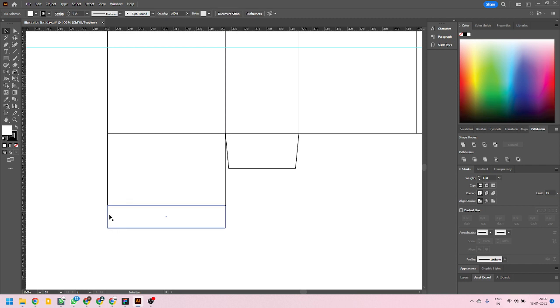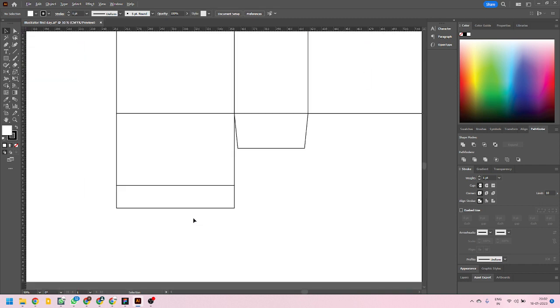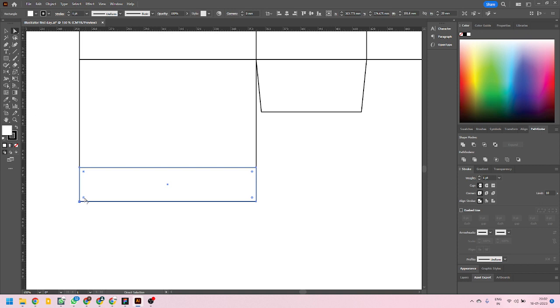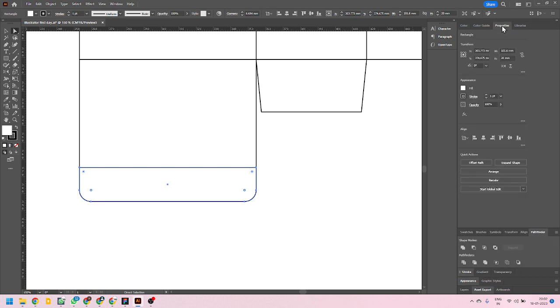Now also, so that it can smoothly go inside the box, it would be a good idea to round it off a little. So I'm going to select this corner handle, these two, and drag. As I drag, if I want to numerically place the value, I can do so by going to the properties panel, and there I have that option. You have to click on this three dot menu under the transform if you don't see these already, and there is the control we are looking for.